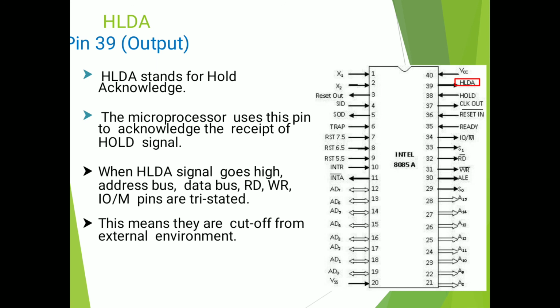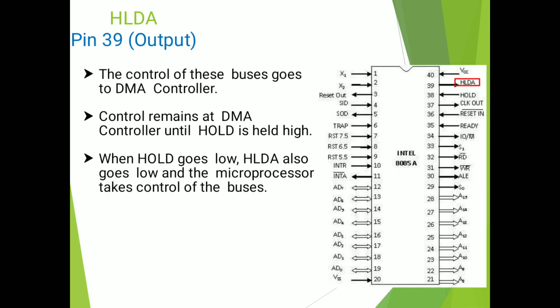When the HLDA signal goes high, the address bus, data bus, read, write, and IO/M pins are tri-stated. This means they are cut off from the external environment.